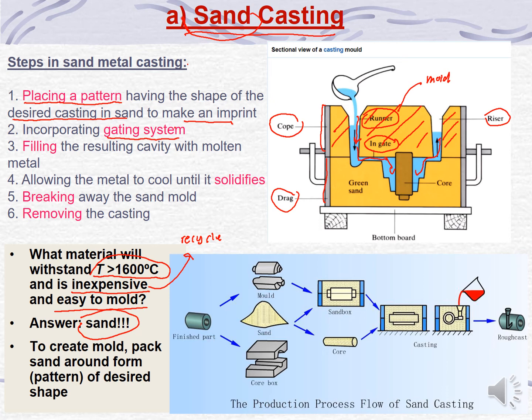Okay, and then we fill the resulting cavity with molten metal, allowing the metal to cool until it solidifies. Once solidified, we break the sand and remove the product.